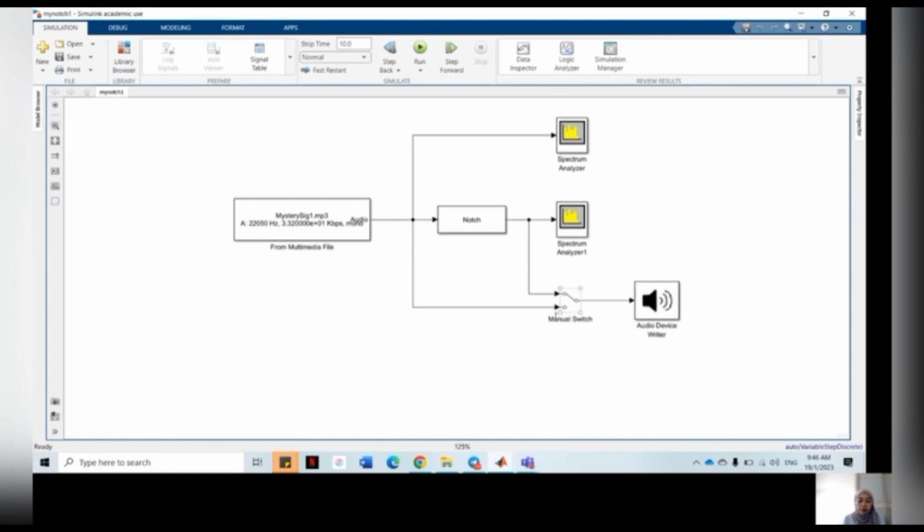We know that the notch peak filter block filters each channel of the input signal over time using a specific center frequency and specific bandwidth. This notch filter design is a combination of low pass and high pass filter, which is similar to the band pass filter design, except it is connected in a parallel connection instead of a cascading connection.